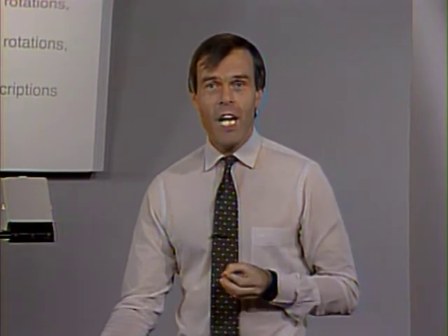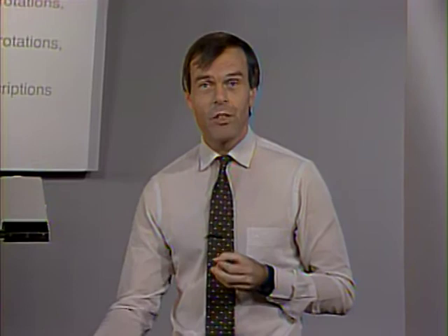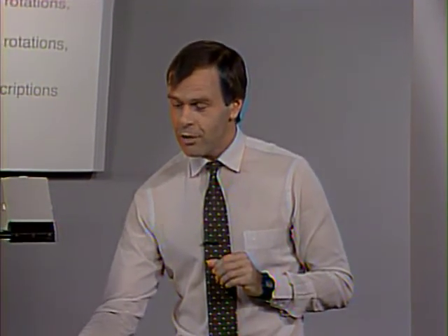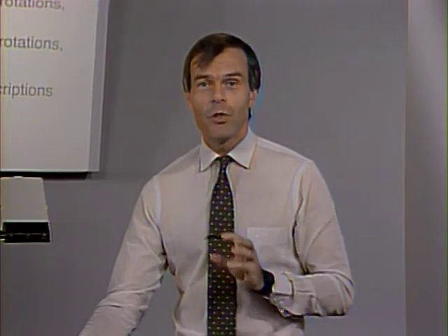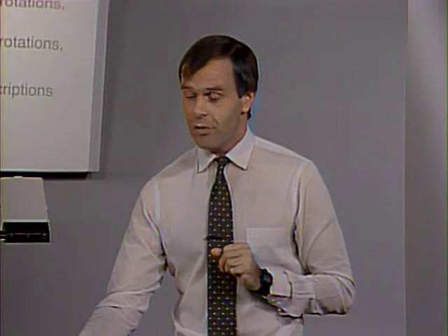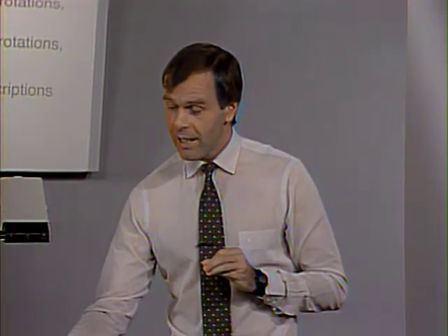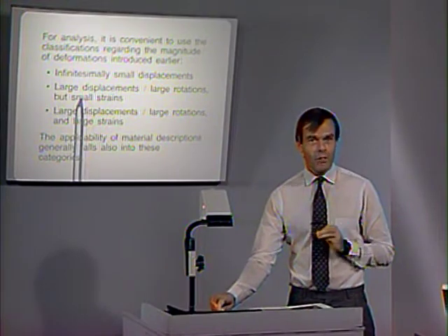If, however, we have a material description that is applicable to infinitesimally small displacements and small strains, then we will see that the same material description can directly be used also in a large displacement, large rotation, but small strain analysis, provided we use the proper formulation. We will discuss this aspect just now. In fact, the formulation that we are using in this category of problems is a total Lagrangian formulation.